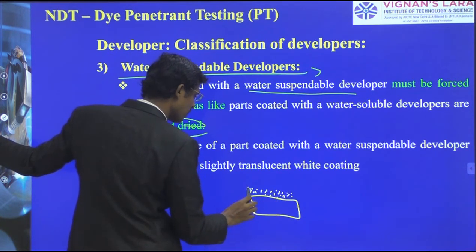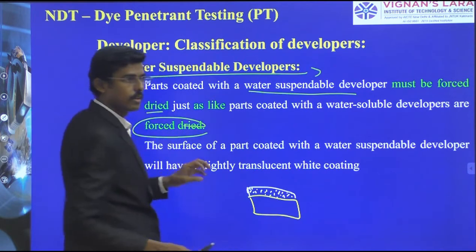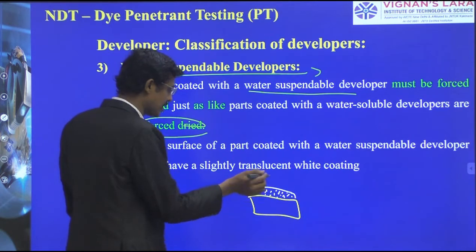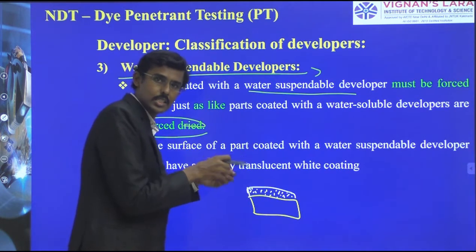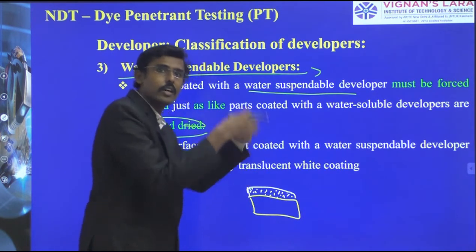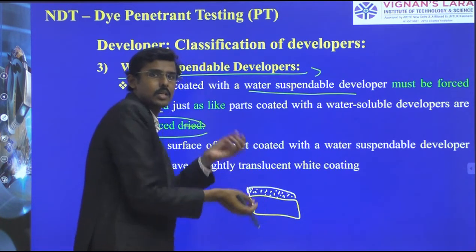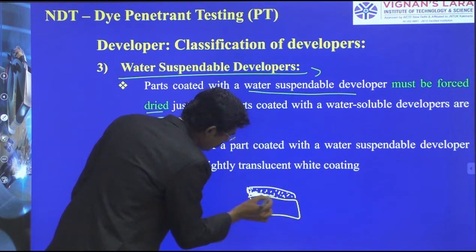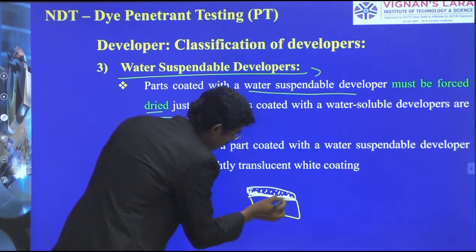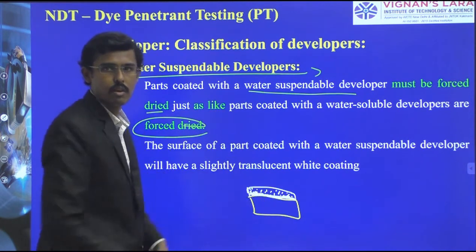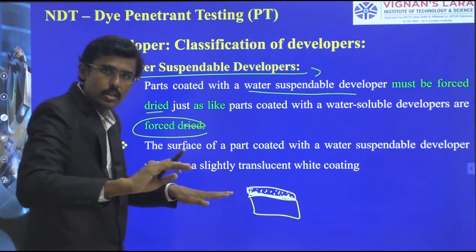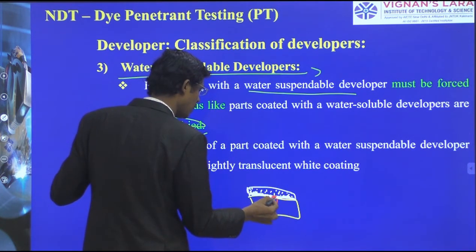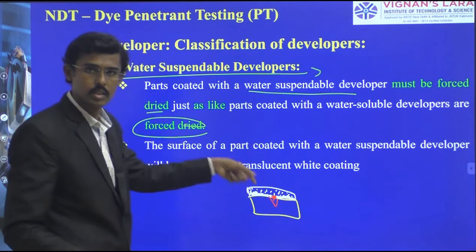When the liquid is evaporated, the particles which were dissolved or suspended will be there as solid particles, because when the water is not there, the powder remains. So it is filling these compounds. When it is evaporated, all the particles fall down and make a solid layer, and therefore the penetrant which is available inside comes out and is absorbed by this developer.